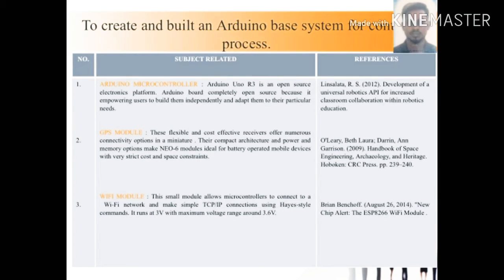The LCD displays have a parallel interface, meaning that the microcontroller has to manipulate several interface pins at once to control the display. This LCD display is designed with 4-bit mode. Moreover, the MQ135 high quality sensor. This sensor senses gases like ammonia, nitrogen, oxygen, alcohols, aromatic compounds, sulfide, and smoke. The operating voltage of this gas sensor is from 2.5 volts to 5 volts.